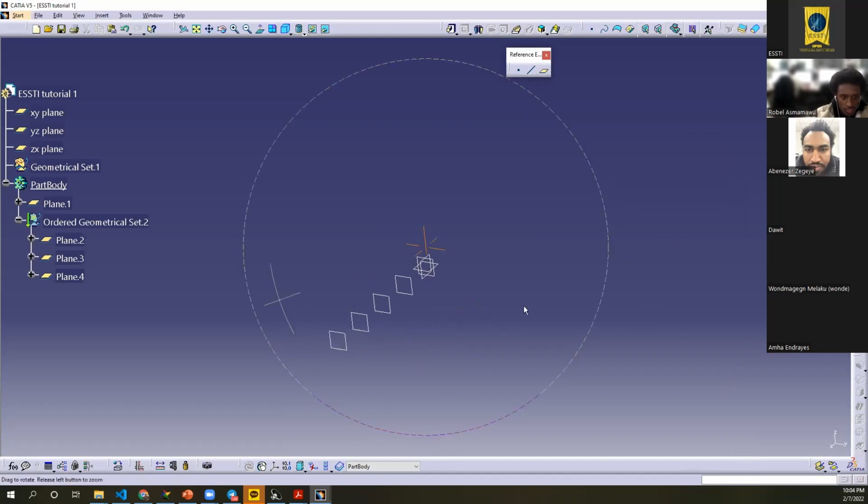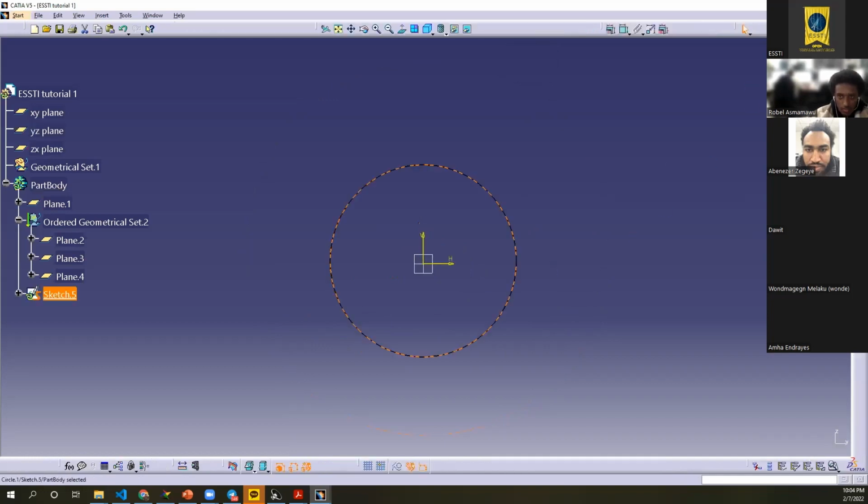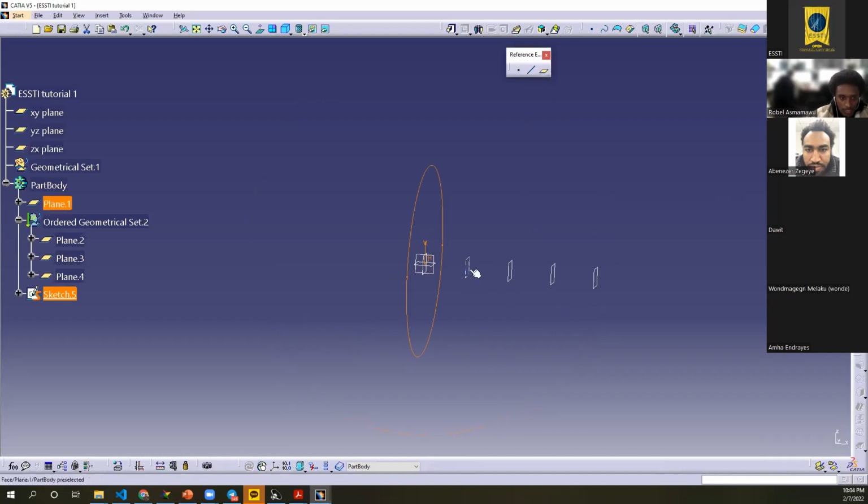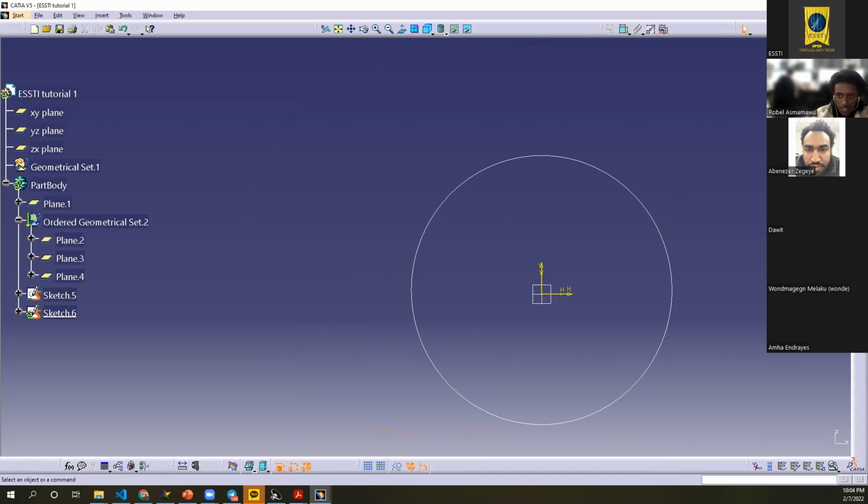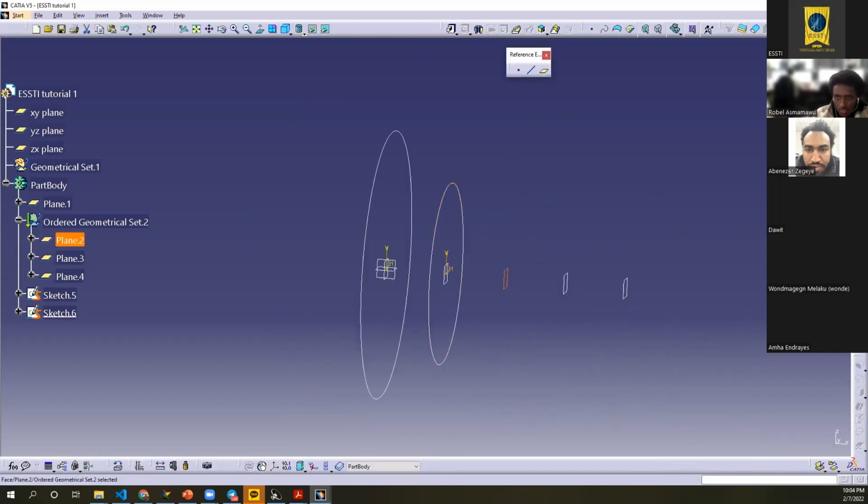And then you can create, let's say, 3, and then you press OK. So now you have created how many planes? 1, 2, 3, 4, 5 planes. This is how you create planes. And then now let's select each plane and make a drawing on it. Okay, I'm gonna select this plane. Circle. Okay, then I'm gonna go out like this, and then I'm gonna select this one, press the sketch button, and let's say I'll make another, maybe something like this. Go out. Maybe select this one.